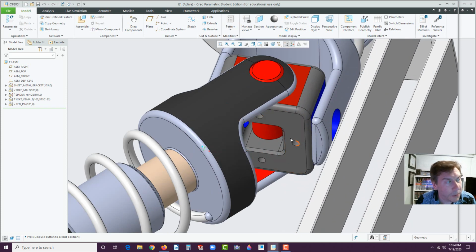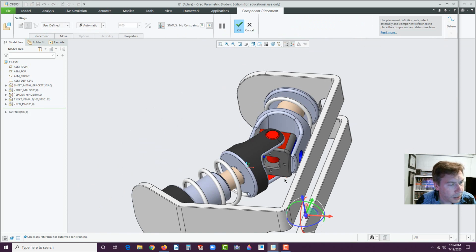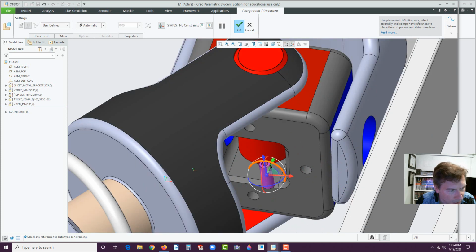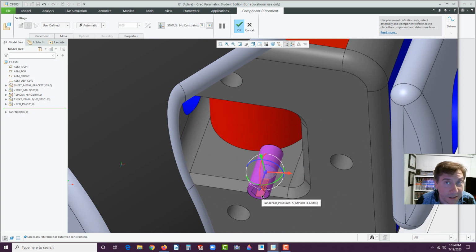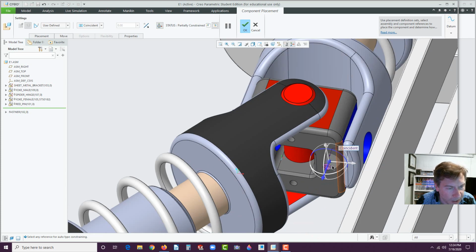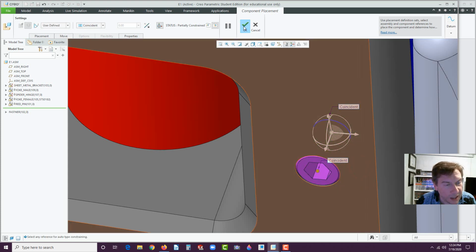There are also some set screws at the bottom, so let's go to Assemble and get the set screws in. It's just the Fastener Pro. Hit open, and there it is. Let's get it close. Zoom up and rotate. I'm going to rotate this so the actual socket is on the outside. Now I'm going to select this face to this face, and then we have to locate. There it is. Let's drag it in close to proximity and then zoom up again. I'm just using the wheel on my mouse to zoom. Now this face to this face, and it went coincident automatically.